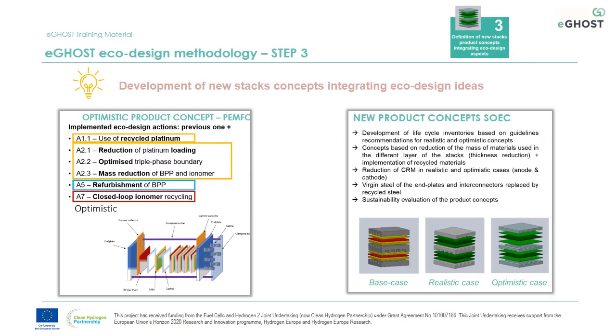Step 3 of the methodology was to develop new stack concepts integrating some eco-design ideas. For example, we had an optimistic product concept for the PEMFC stack with some implemented eco-design actions, such as the use of recycled platinum, the reduction of platinum loading, the optimization of the triple phase boundaries, a mass reduction of the BPP and the ionomer, the refurbishment of BPP and the closed-loop ionomer recycling.